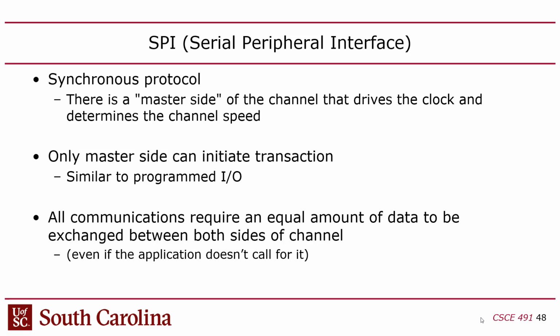Then I talked about SPI. It stands for Serial Peripheral Interface. I mentioned that SPI is not governed by any kind of standards body. It's what they call a de facto protocol. So it's totally unregulated, and as a result of that, you see a lot of variations on SPI depending on the chips you buy. It's not very consistent.